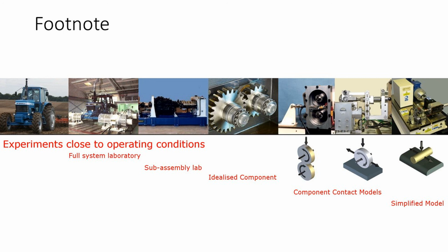We can usually manage to characterize frictional response relatively quickly, but it usually takes a long time to generate wear or failure in real systems. Hence, sensible wear tests are likely to take a long time. It follows that if we can miss out any of the steps between real system and simple laboratory test, the potential for saving both time and money is enormous.